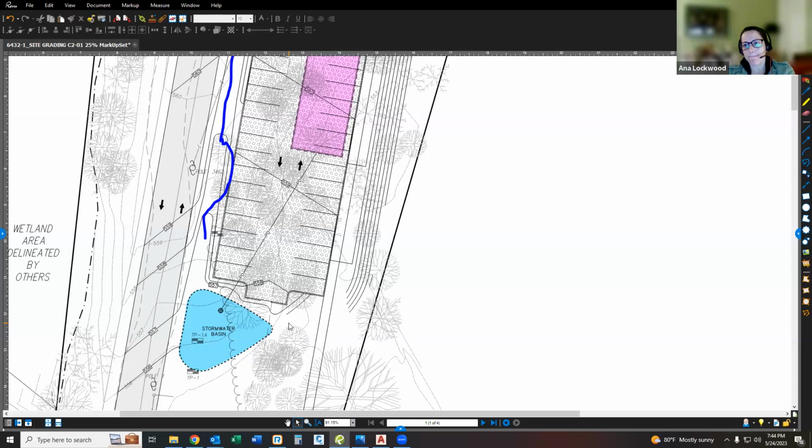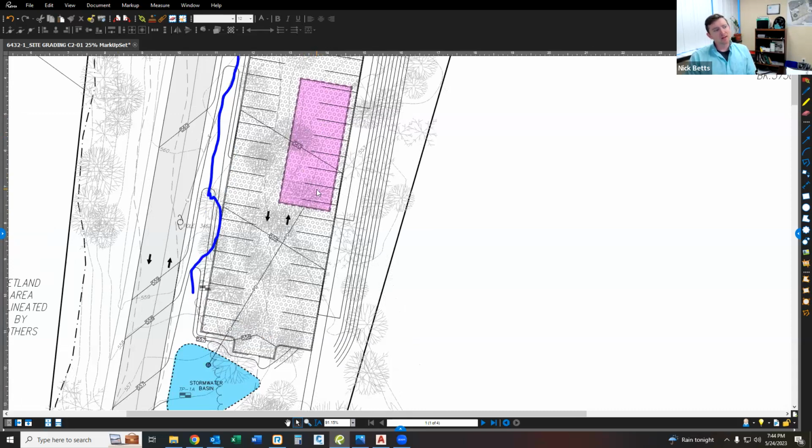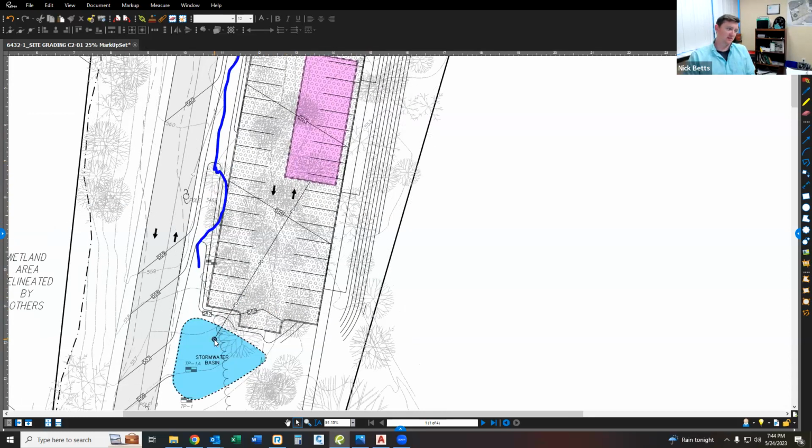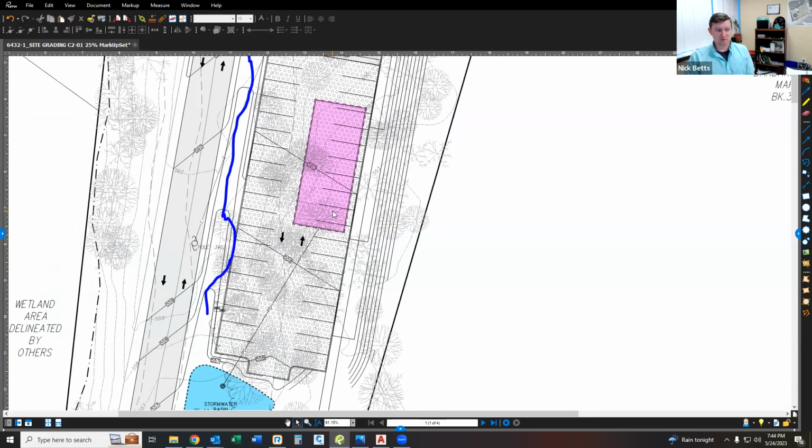Yeah, so maintenance is always an issue with every system, and every stormwater BMP has some level of maintenance that is required. The chamber system itself, it's rare that it fails that quickly. What we've seen happen is that your clog will happen in the inlet, and as soon as the inlet gets clogged, you'll know, and then you alleviate it from the source of where it enters. The systems themselves are only susceptible to the water that gets into them, so it doesn't really seem to clog the systems.